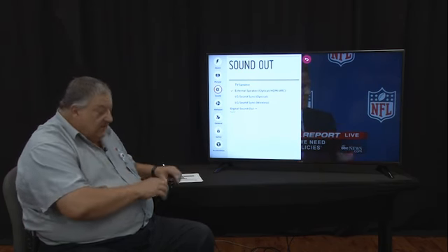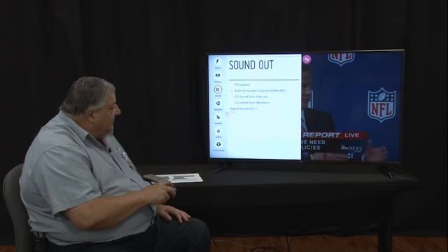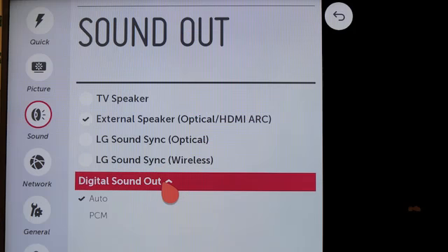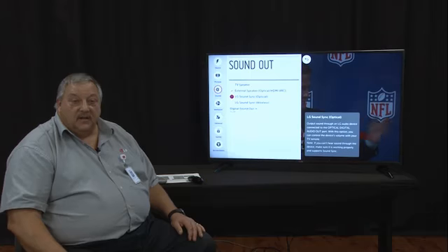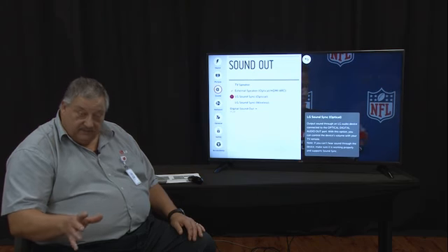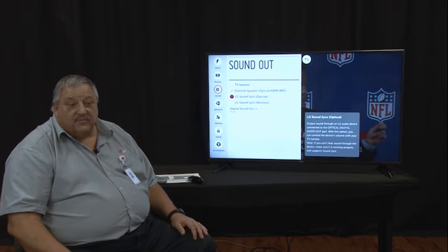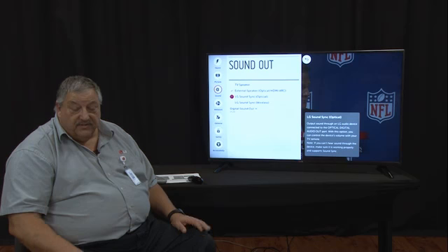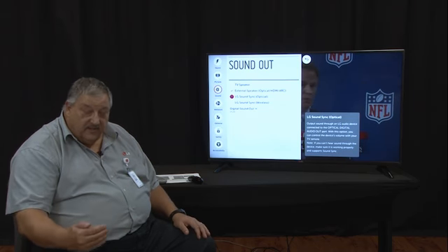And by the way, let me mention one other thing while I'm here. If you go to the digital out, you only have two choices: auto and PCM. Now, if you fix it on PCM, as long as there's PCM coming in, it will be on PCM. No matter what the service menu says, it'll be on PCM if it's present. Now that would be customers with that sound bar I mentioned that only processes PCM.